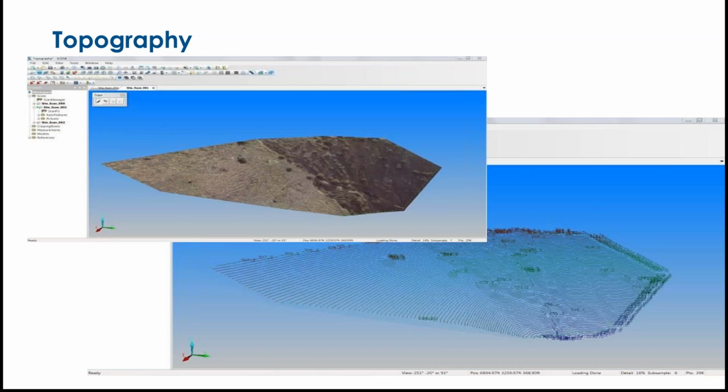The other side of that, which is a little hard to grasp at times because of the way we're used to working with our applications, is that point cloud data is a little bit too much when we're talking about tins and surfaces in Civil 3D. So we do have to simplify that data to a degree. Generally, what we would do in Civil 3D is create a surface from the entire point cloud. And then from there, we would start extracting points at the necessary features of the land. That would build a tin that is more aesthetically pleasing because we're used to dealing with simple contour lines.